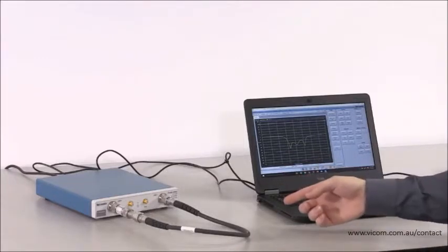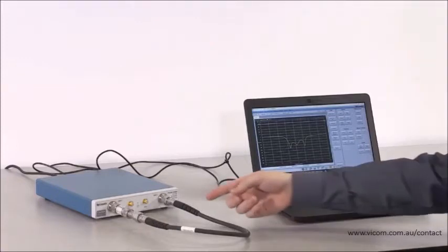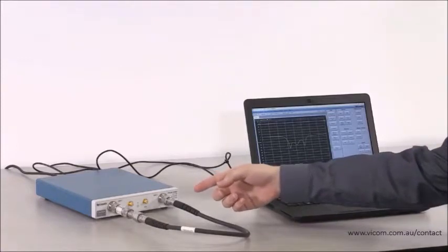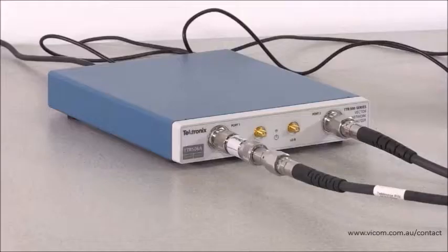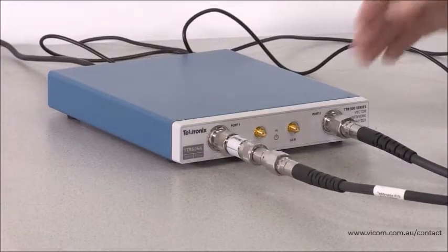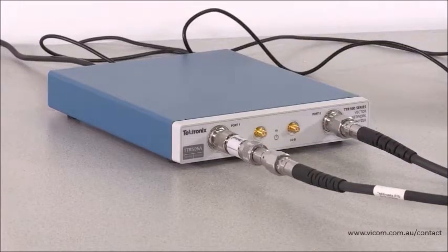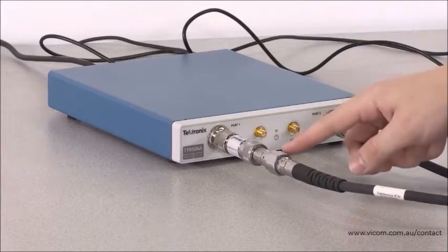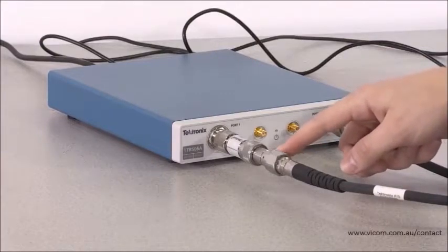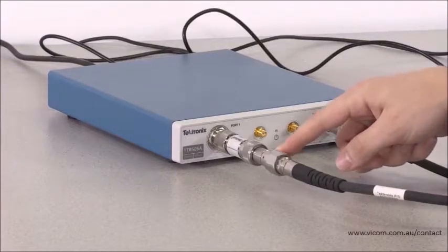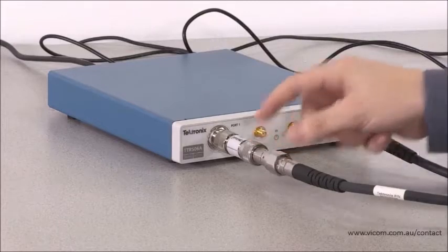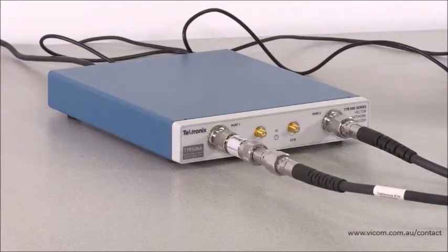And I've got an N-type phase-stable cable connected to an adapter that's connected to the bandpass filter on port 1. Prior to making a measurement, I performed a full two-port calibration on port 2 and port 1 of the VNA up to the dot. And in order to account for the change in adapter used in the calibration versus the measurement, I performed a port extension to compensate for the change. See how to make a full calibration and port extension in our previous videos.